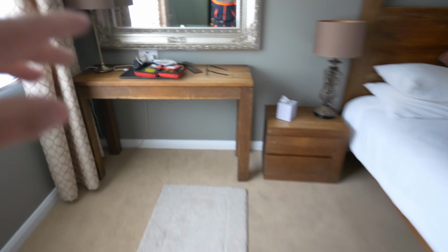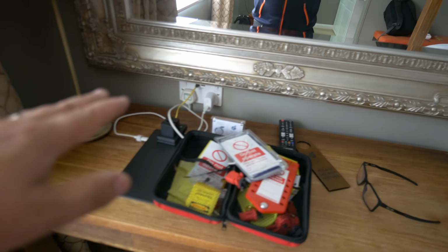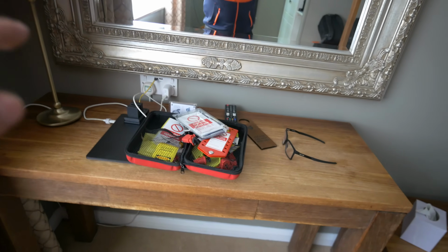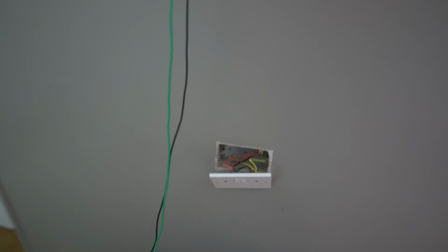Now obviously if they're tiled in or there's some nice wallpaper and paint and you're not too happy about removing it through the prospect of causing any damage, then you need to note that in the limitations section as well, and make sure you agree it with the client. They may say it's fine and that you can pop the socket off and not to worry about it, but we've all been there where there's damage to wall surfaces and people start complaining after the fact, so make sure you have those conversations.